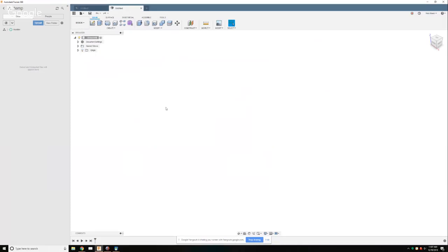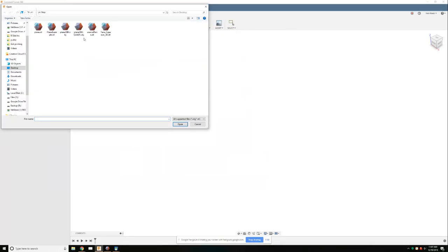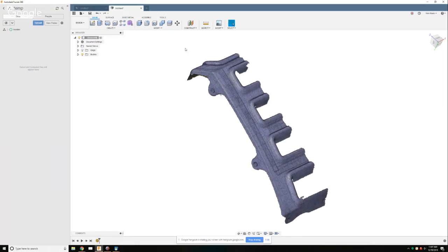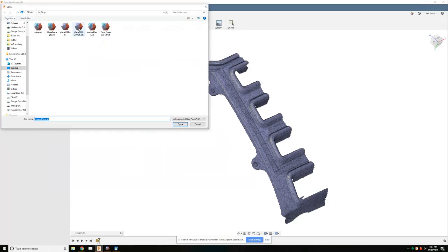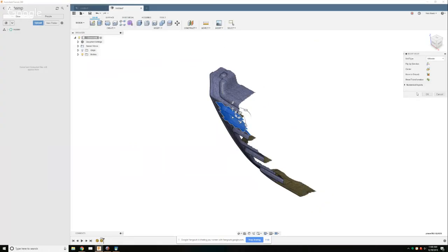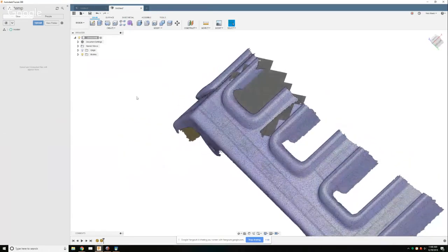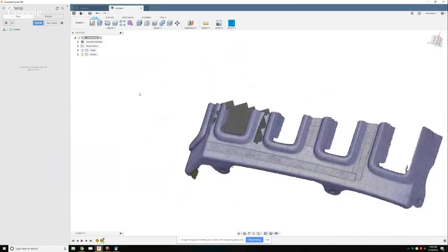Now let's go into Fusion. What we would do in Fusion is insert the source plane like this. That is great. And we will also insert the mesh of the plane quads. And that came in right there. And you can see that that is perfectly aligned because it kept the coordinate system.